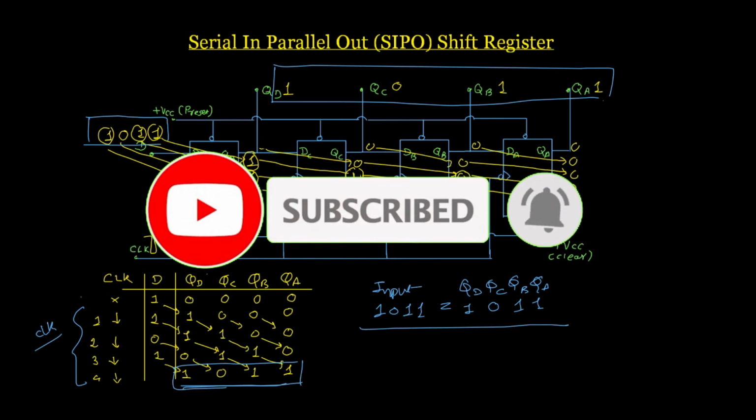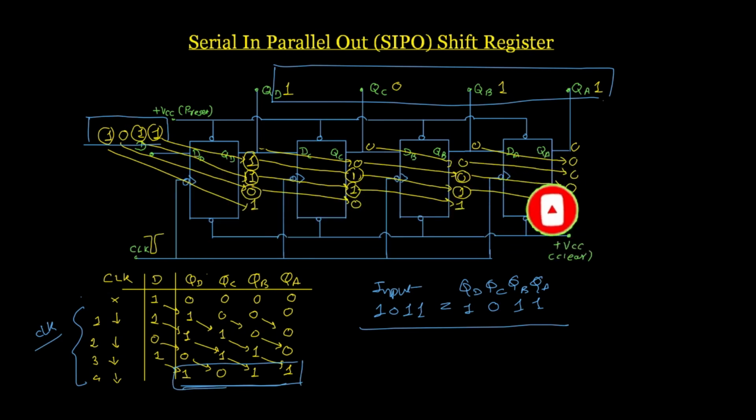Whatever your data is, it appears at the output after the fourth clock pulse in parallel. In a serial output, you require some more clock pulses to get the output. So this is known as serial in, parallel out: the data is entered in a serial fashion and we get the output in parallel fashion.